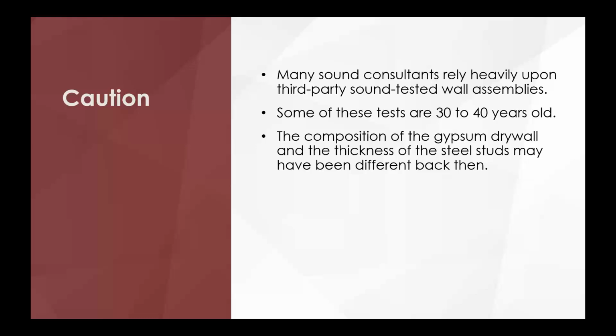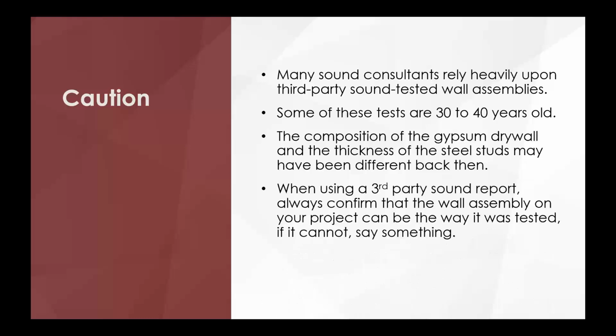The steel thickness was definitely different. So there are some differences in there. When using a third-party report, treat it just like a fire-rated assembly. And what I mean by that is look at exactly the way it's built to make sure you could build it that same way. For instance, you might see some sound reports will have a 1.25 inch bottom track used for the head of wall.